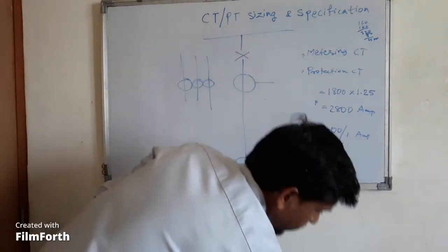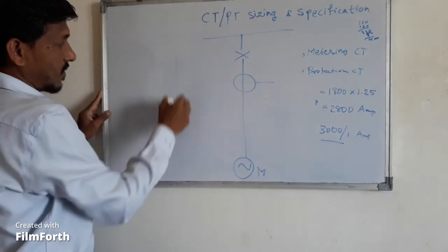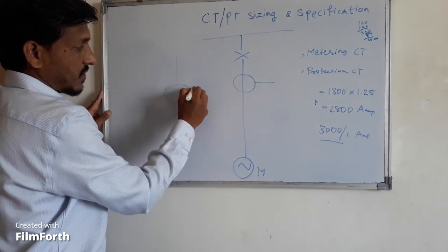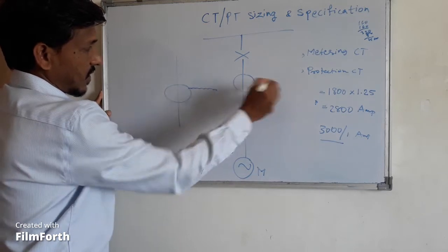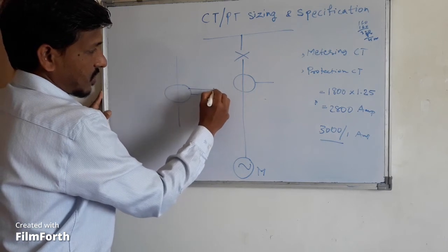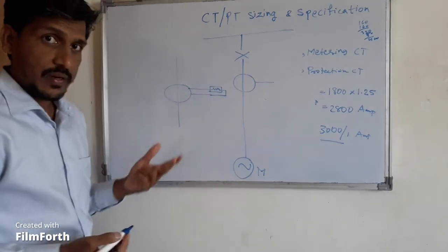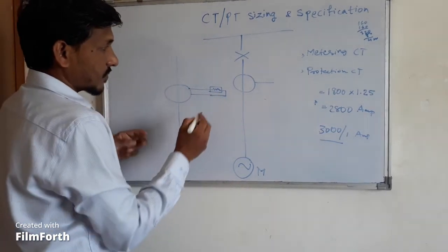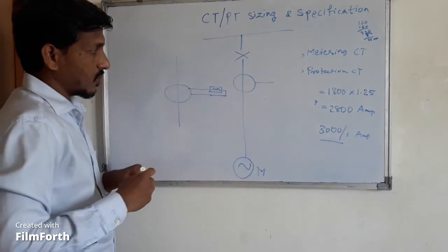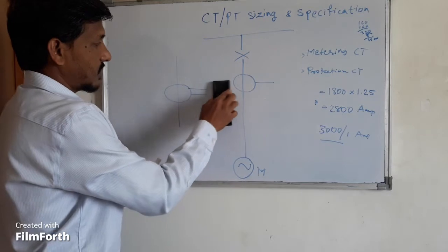Is that clear? So basically this is a single conductor. Across it the CT core is there, and on this core there is a secondary winding which is connected. This is shown in the single line diagram as a single line. The secondary winding is connected like this, and across this a meter is connected. This is a meter, or an ammeter, or even a relay in a protection CT. So this is the figure in the three-line diagram, in a detailed way. So how to specify a CT rating? We'll see it in much detail here.